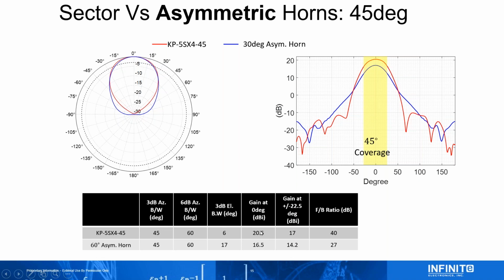You get a 4 dBi increase over the asymmetric horn. Even though the point of doing the asymmetry is to increase gain, you're not reaching the gain of a sector, even though the size is very comparable now. It's funny because these asymmetric horns are really long, and you're pretty much trying to reproduce the pattern of a sector antenna at this point, but at the same time you're not getting much. I mean, the front to back degrades so much from the symmetric horns.